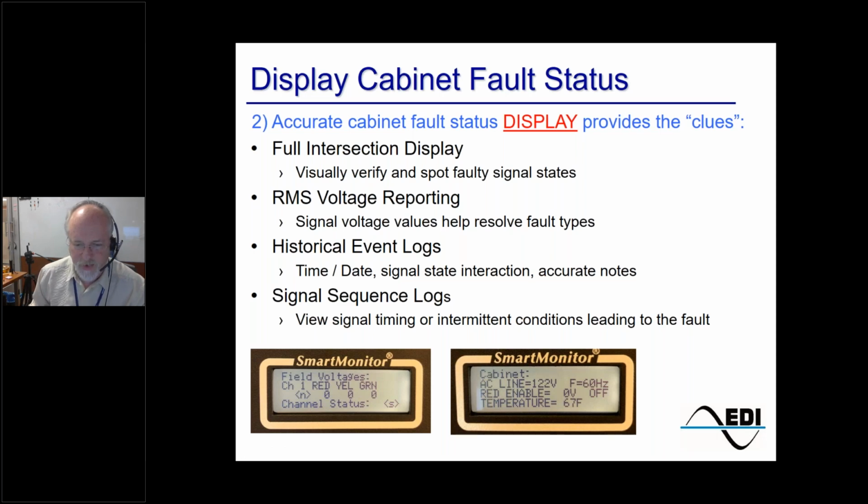Well, the other thing that this is looking at is the output, or the bulbs. I've seen leakage voltage over an LED head too. So if you replace the load switch and it doesn't change, then you need to start looking at the 2 to 3 heads that are out in the field to see if there's a problem with that.